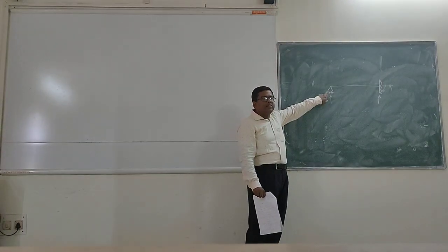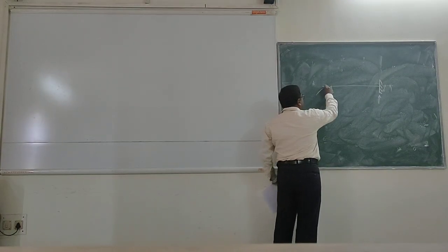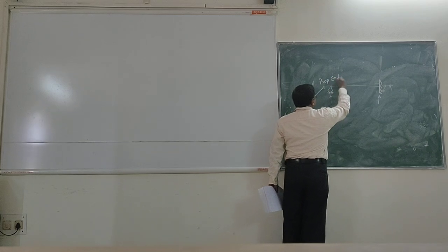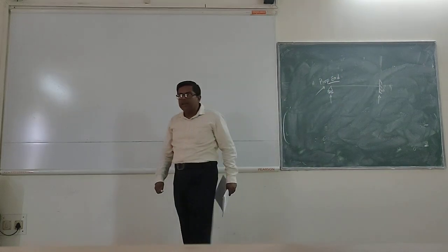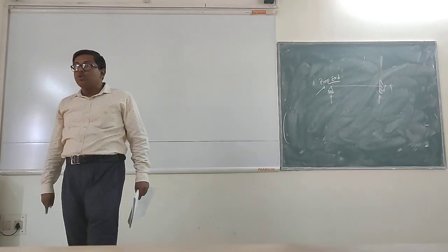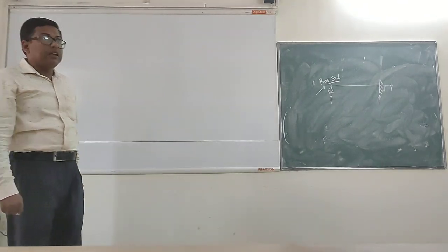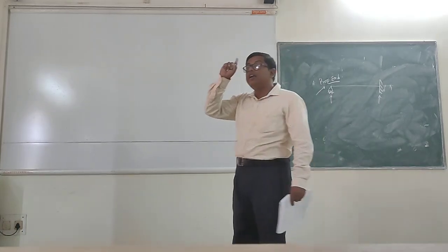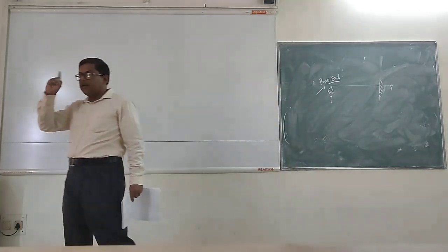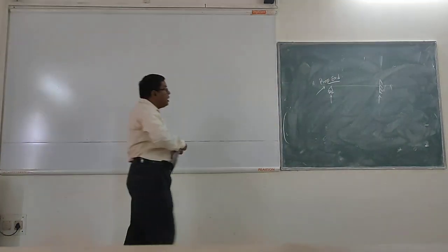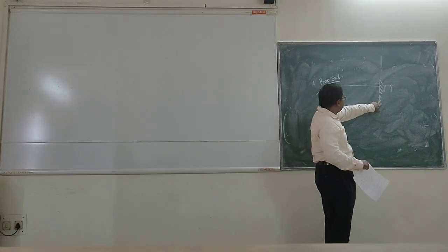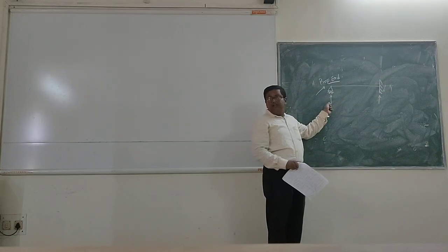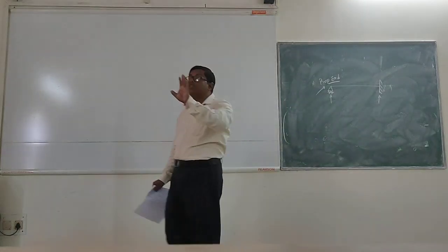What is this end called? This end will be called the prop end, and this cantilever will be called a propped cantilever. If you see, it is not a determinate structure. It is a 1 degree indeterminate structure. Why is it 1 degree indeterminate? If it is a cantilever, then you can solve for this and this using the equations of statics. But this reaction you cannot solve using the equations of statics.